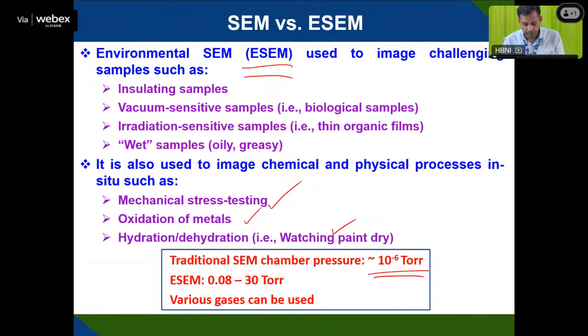And in the scanning electron microscope, there is a raster scanner on the top surface, and that scanner collects the data pixel by pixel, and it is added up and displayed again on the screen, and you're able to get a 3D or reconstituted image. So this is mostly about the scanning electron microscope.